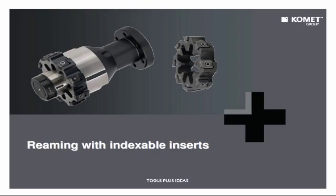A last tool I'd like to introduce to you, reamer rings like this. These reamer rings are normally braze type. So the cutting edge is fixed by a brazing operation, and after brazing we do the finishing. We have such reamer rings still in our program. We do the finishing according to your diameter, what is required by you, into a tolerance of, let's say, H7, H6.